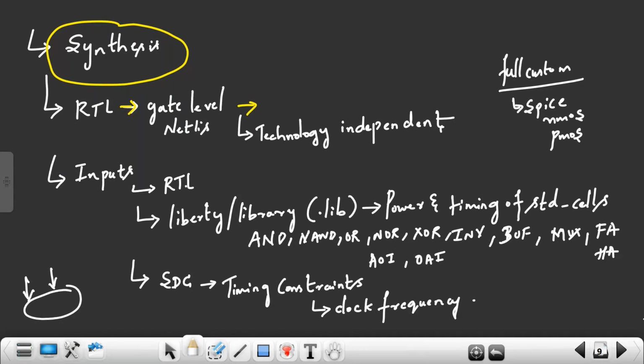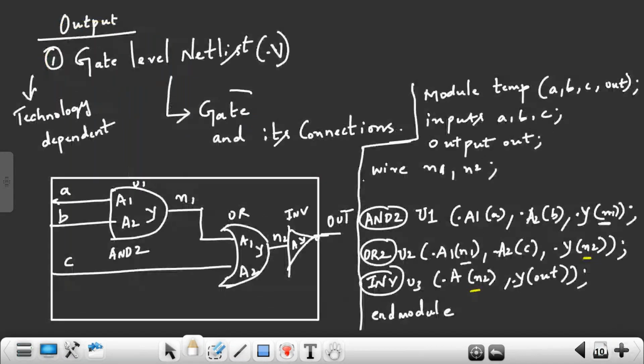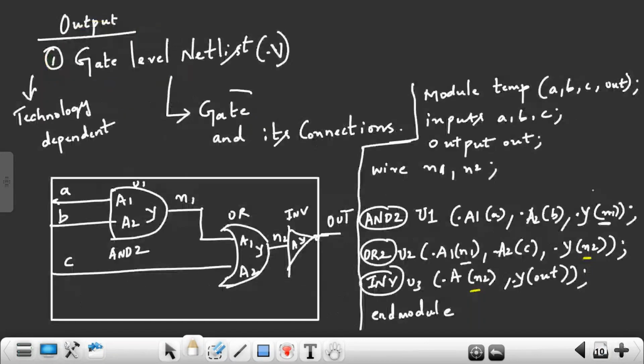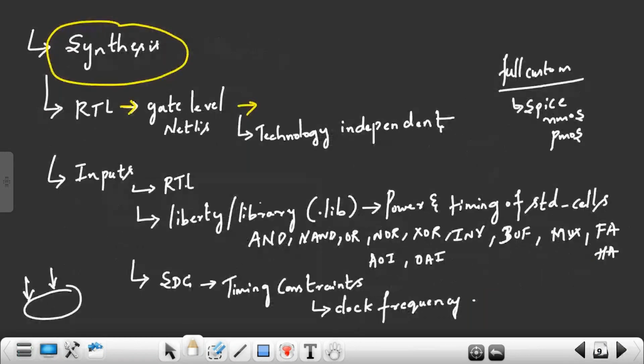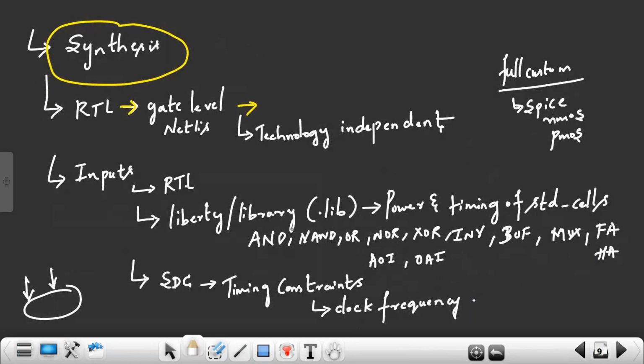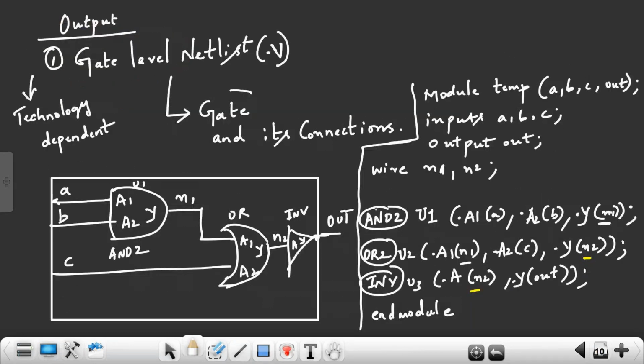So this was done for 7 nanometer and for only this Liberty file. I can use it only for this Liberty file. I cannot use this netlist for different Liberty files. See, I cannot use the netlist independently. If I use the netlist, along with it my Liberty file should be present. Then only my tool can understand this is an AND gate. Only the name will not tell this is an AND gate. So if this is an AND gate, my tool will look to the Liberty file. In this file only I will have information about this gate: what this cell will do with this name.